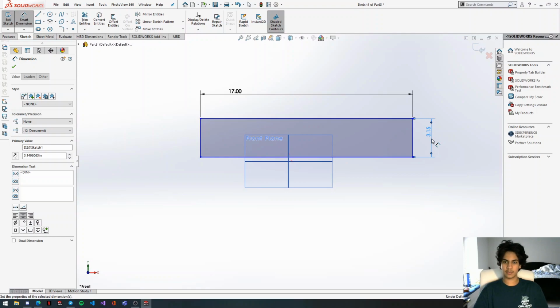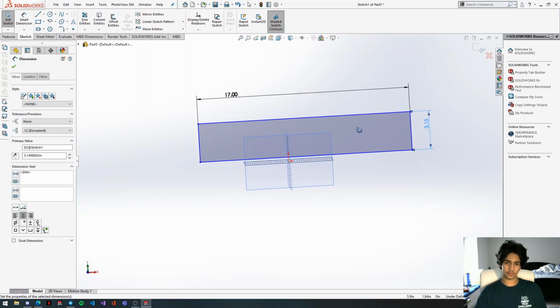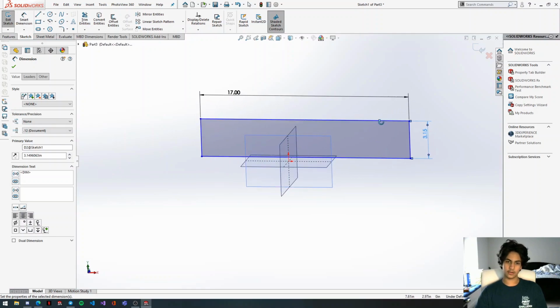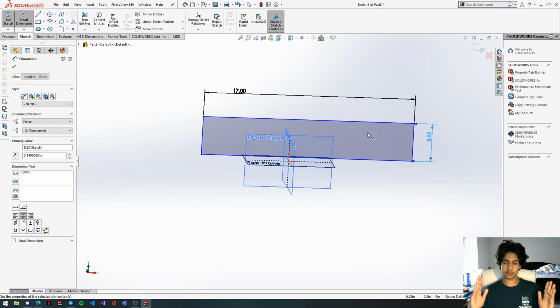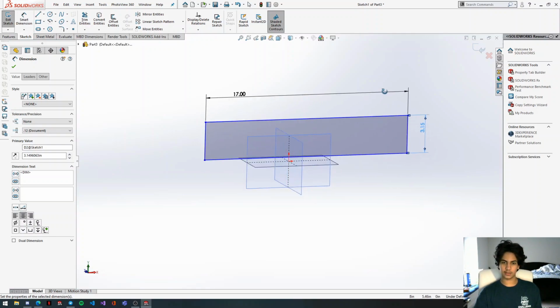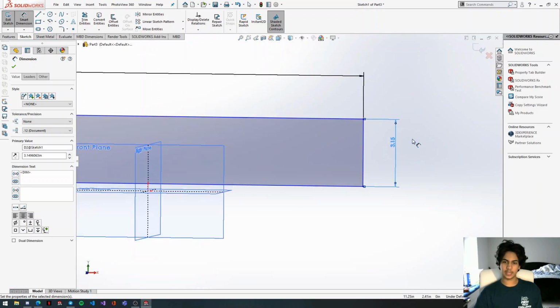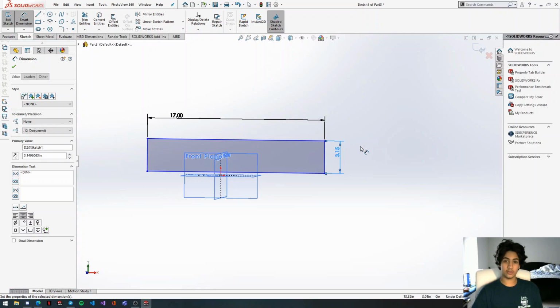Whenever I have to be mindful of whether I'm going out of bounds or not, the drive plate is pretty much the longest part you'll probably have on your robot, unless you have a virtual four-bar or something. Width wise, I want to make absolutely sure that I have enough space on either side to fit in the size constraints. But everywhere else, I tend to use metric, unless I contradict myself in later tutorials. We set this to 80 millimeters because the mecanum wheels we're using are the goBILDA ones, which are 100 millimeters. So that gives us a good 10 millimeters on the top and the bottom of the parallel plate.